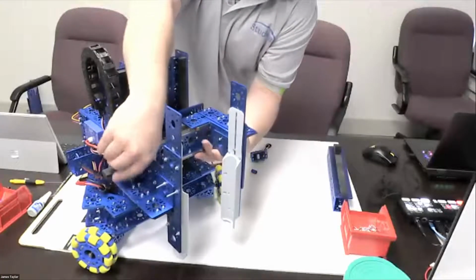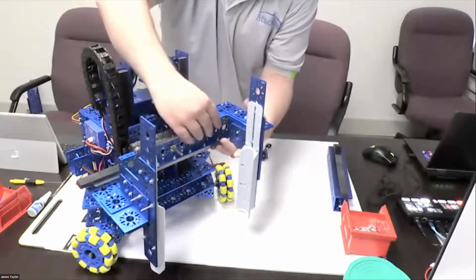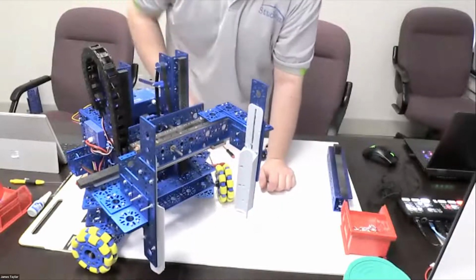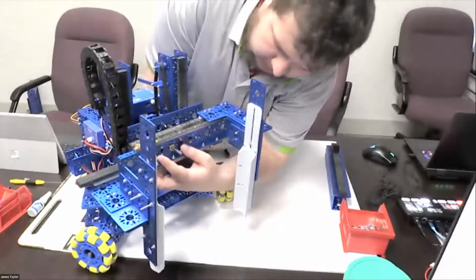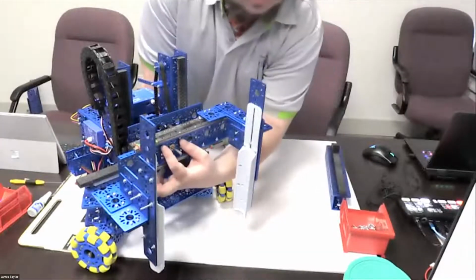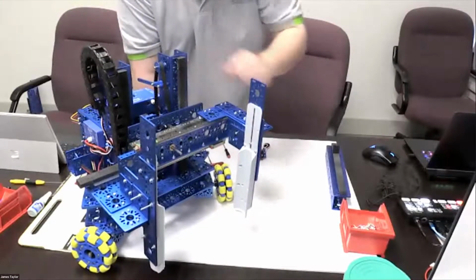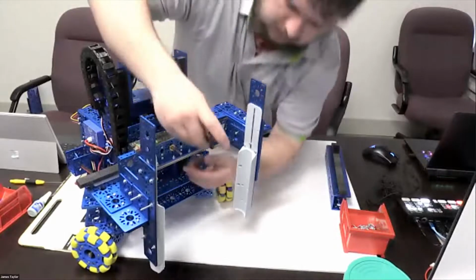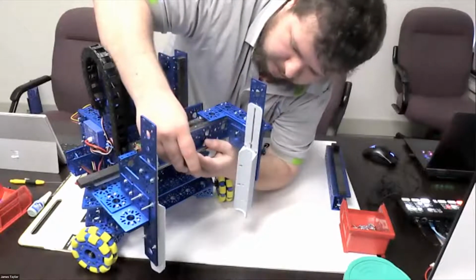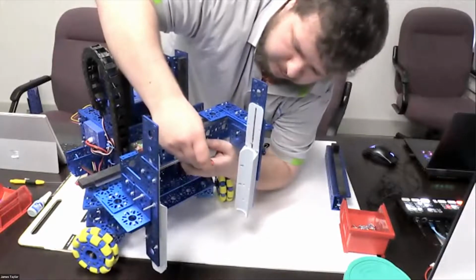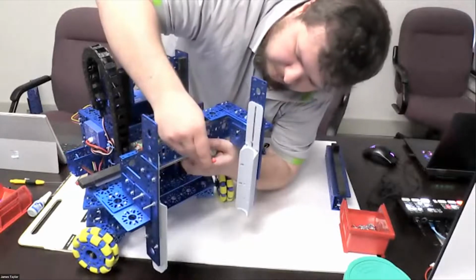So we have the slide mechanism here. Once attached, there are some screws here which hold the main slide plate to the flat plate. You want to make sure that they're tightened properly in a star pattern. This is to create an even torque amongst them. My screws were a bit loose.